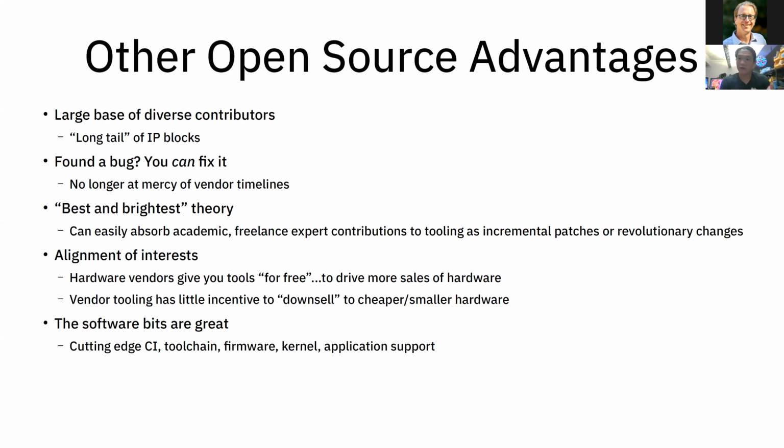So when they give you IP blocks, a lot of times when they compile, the options to actually take out bits and pieces you don't need aren't there. So you'll get an IP block and it'll take a huge portion of the area on your FPGA, and you just have to carry that. And if you want to put more in your chip, well, you have to buy a bigger chip, which is great for the vendor, but not great for you.